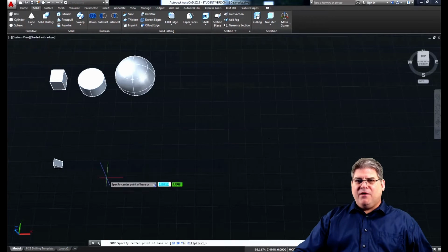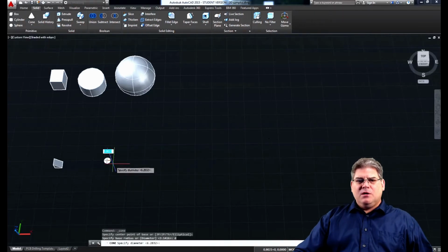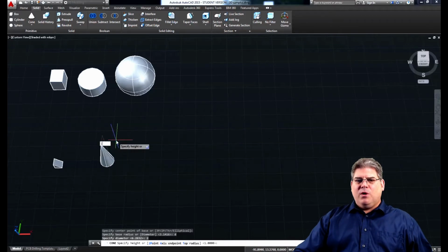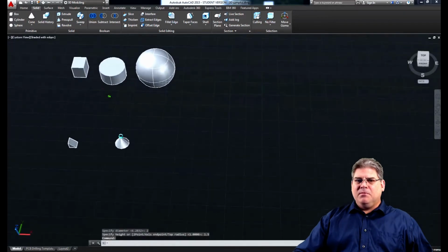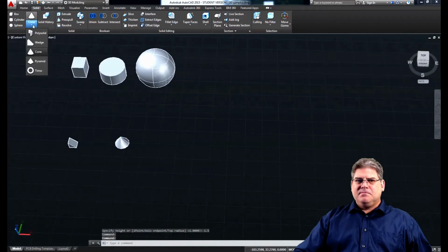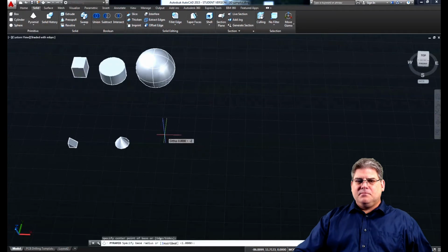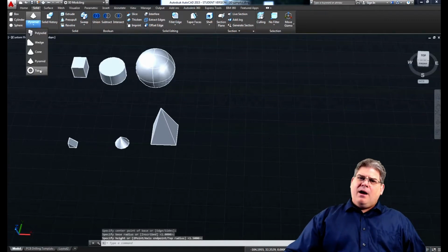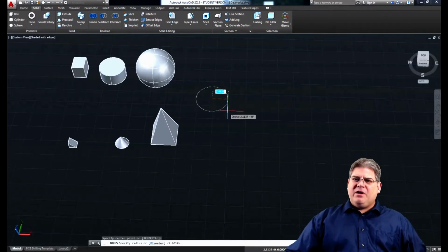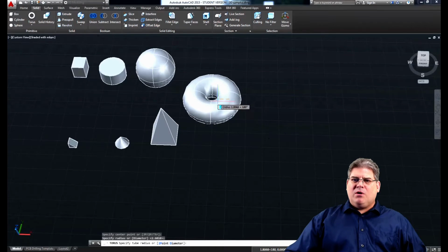And of course, we have our drop-down menus, the same as so many other functions with AutoCAD. And here we're able to create a cone. And again, we're able to type these values in if we know them. I will have you note that I have tilted everything around, so I'm no longer just panning.